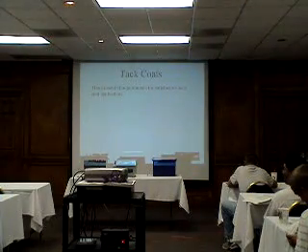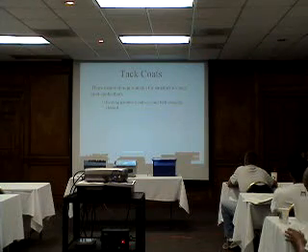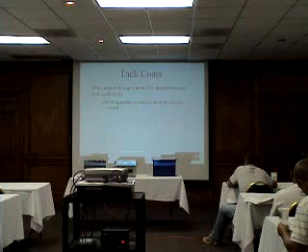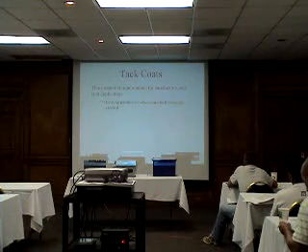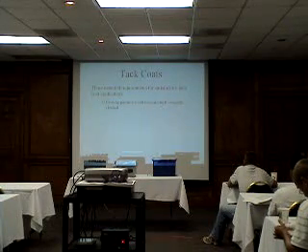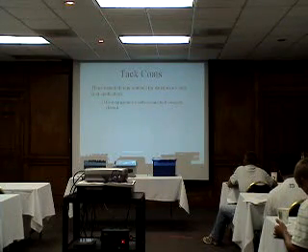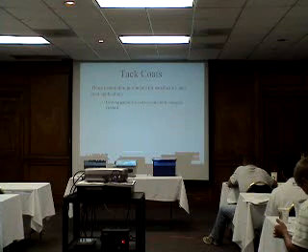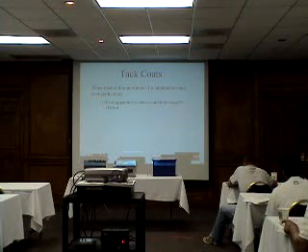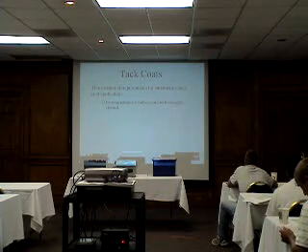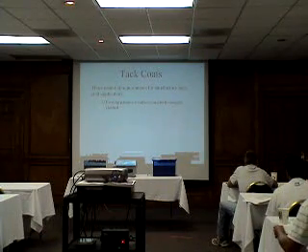Three essential requirements for satisfactory tack application. The pavement must be sufficiently clean. Must get rid of all dirt, clay, mud, whatever that may be on the existing pavement. Because if you don't get it clean, when you put the tack coat on it, what's going to happen? The areas where that mud and dirt are, the tack's going to be sticking to it and not to the underlying surface.